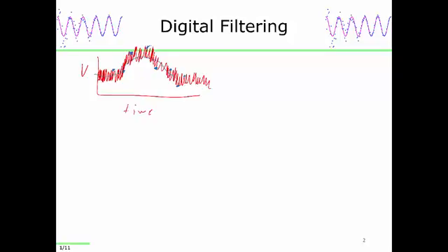Why is this a common problem? Well, we have high-speed electronics. A digital oscilloscope can sample very quickly. Why not run it at full capacity, irrespective of the bandwidth of your signal? So the answer is there's really no reason not to sample at the full bandwidth of the electronics, because there's no signal-to-noise advantage to undersampling if you're not doing something to affect the bandwidth.